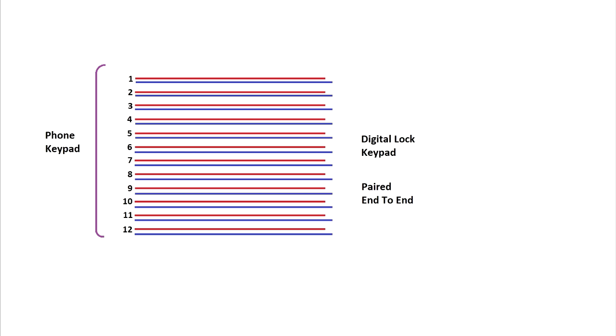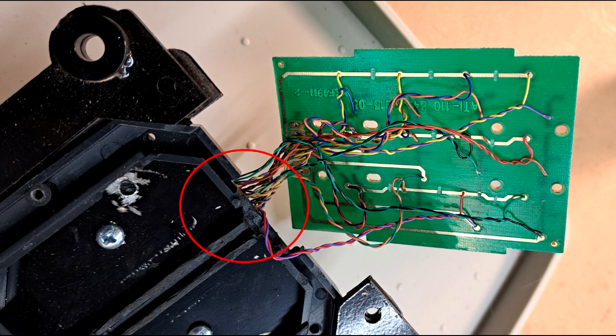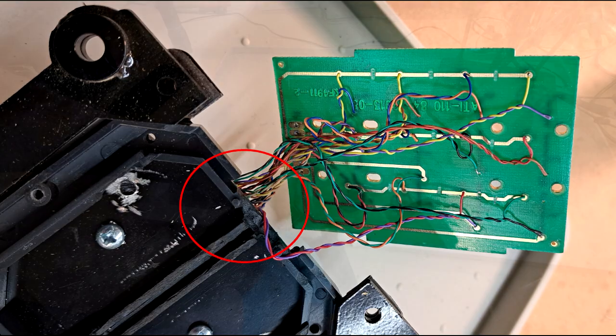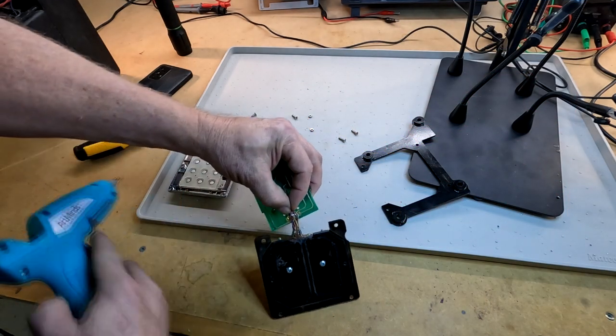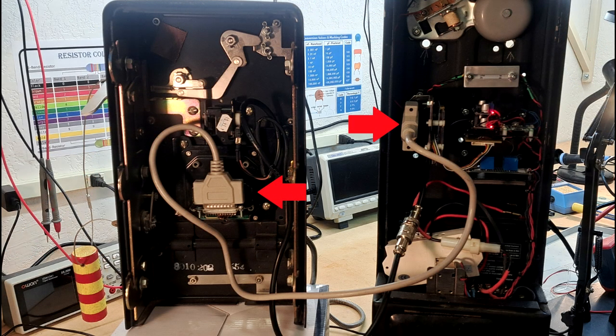If you are not well versed in electronic knowledge, this is the simplest way with the least questions, even if it means using redundant parallel connected wiring. Grind away some of the rear plastic housing to make room for your new wiring to run out below. Hot craft glue can be used to secure these wires to the board to protect them when you finish. You will need to periodically remove the upper detachable portion of the phone for maintenance and battery replacement.